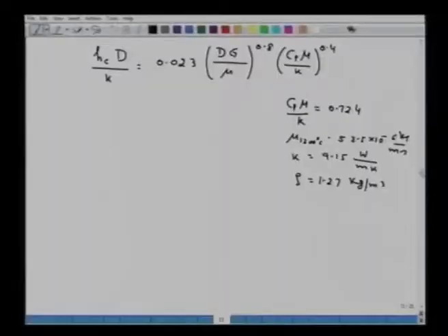So, here dry air contains oxygen and nitrogen, and heat transfer will purely occur by convection, because for radiation to occur the triatomic gases like CO2 and H2O should be there. So, in A you have to calculate the heat transfer by convection, and first of all you have to calculate the heat transfer coefficient, and this correlation I had already given in my earlier lecture.